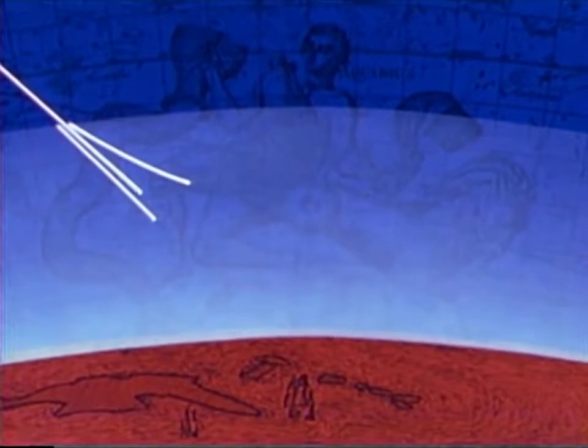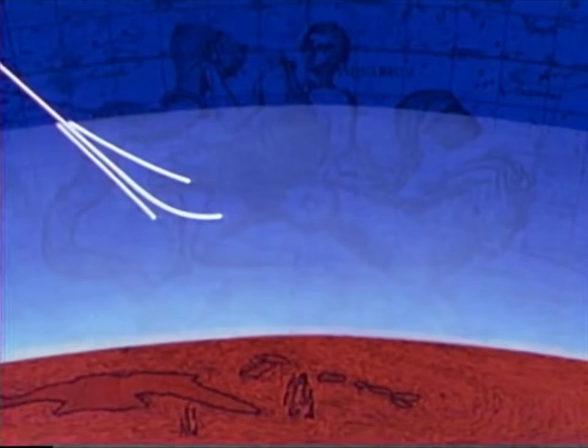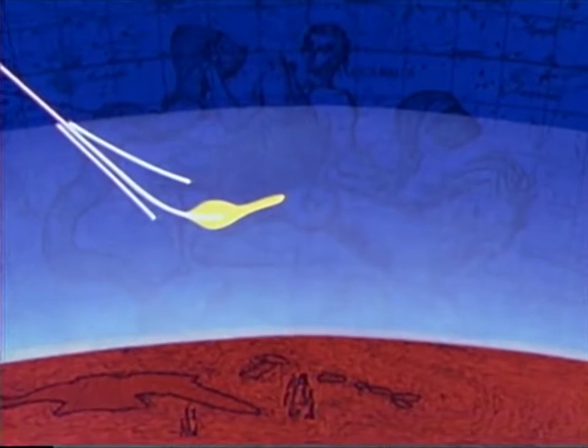Just before pull-up, it enters the atmosphere dense enough to allow aerodynamic control of its landing point and begins its first control period. The command module will then climb until it skips out of this denser atmosphere. The skip is primarily to increase the maximum range of the spacecraft and to reduce the aerodynamic heating load on the heat shield.